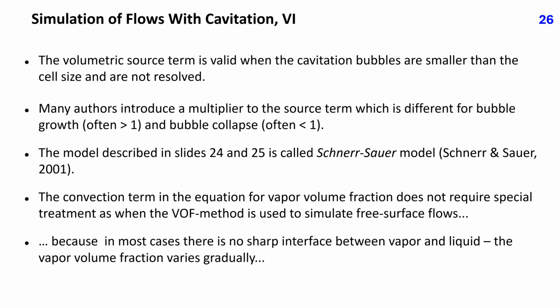The convection term in the equation for vapor volume fraction does not require special treatment as when the VOF method is used to simulate free surface flows, because in most cases there is no sharp interface between vapor and liquid. The vapor volume fraction varies gradually.